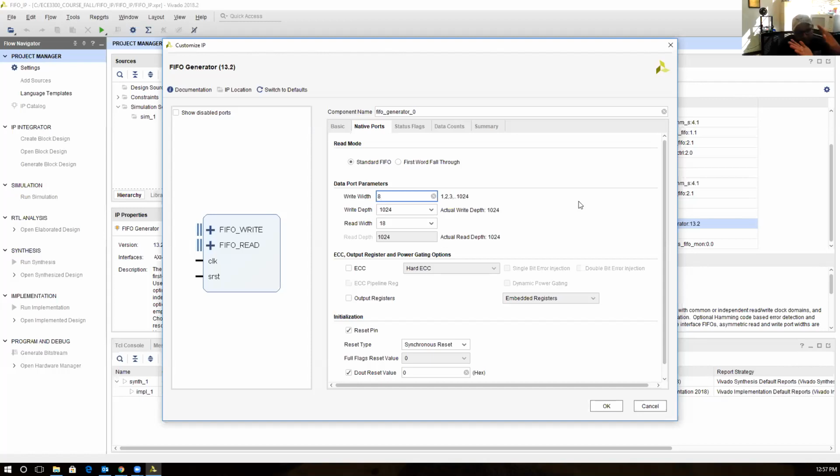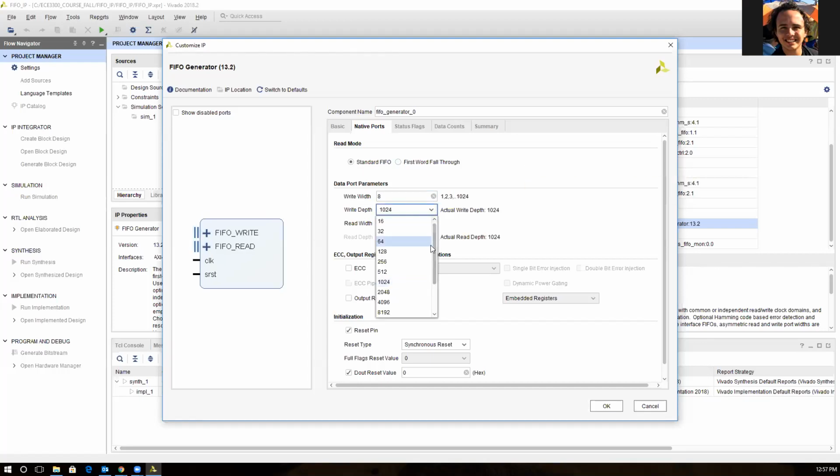So that means 501 is taking the bits from 0 to 1023, while 502 is taken from 1024 to 2047, while 503 is taken from whatever. That means you're going to have multiple FIFOs generated, not just one block and that's it. You're going to have multiple blocks. Then here's your depth. Your depth is up to a big number, basically.